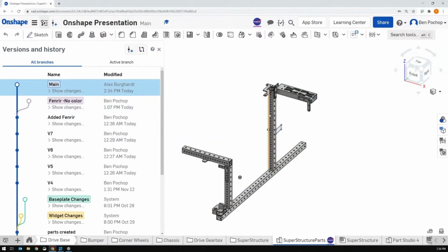So both of those changes that happened in different aspects get carried over and work back together. Now, again, simple, simple, simple, but you can envision a place where this is a bracket for part of our climber mechanism up here. You have 3 or 4 different teams create a branch and work through some different iterations of this climber. And maybe one comes up with a really good way to connect it to the base frame. Another one comes up with a really good way to connect it up here. You can merge those changes back together and have them carry over and attach to each other, which is kind of nice. You don't have to do a bunch of assembly deletes and adds and moving things around later on.